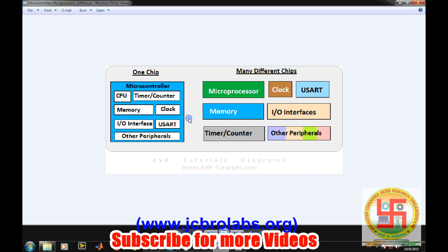Microprocessors are meant for general purpose or bigger applications, like running an operating system on them. We can't run an operating system on a microcontroller because microcontrollers are designed for a specific requirement with some constraints. They have constraints of memory and input output interfaces, while we have fewer constraints as far as memory and other things are concerned with the microprocessor. This was the basic difference.